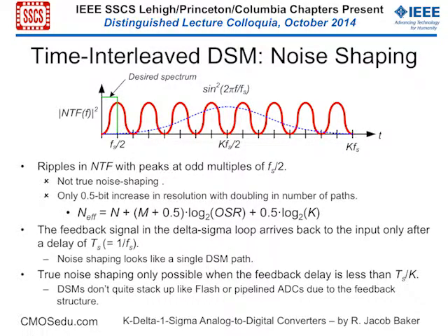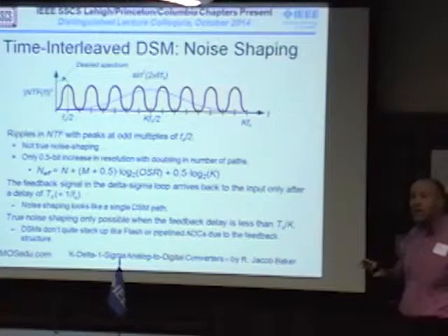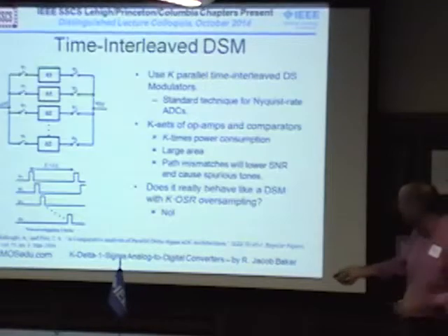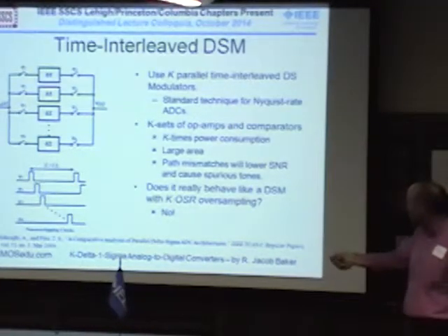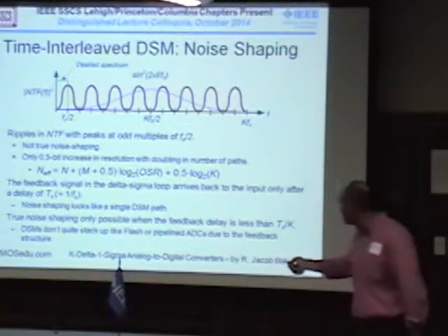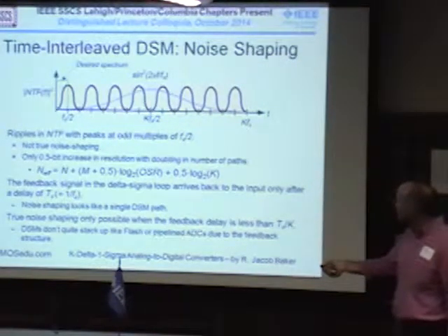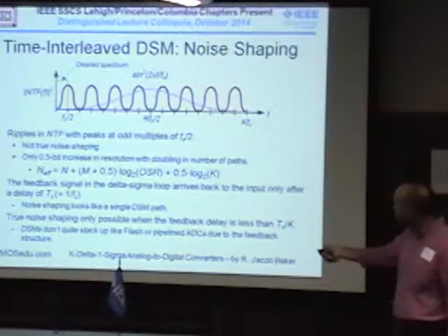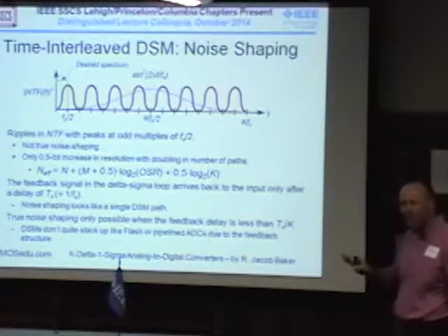What we want is what's in the blue. Because if we can get what's in the blue, then we've pushed the noise out to higher frequencies, and we've effectively increased the sampling ratio. There's papers that I reference here, there's this paper here that did this and proved what we're saying here. We built it and tested it. So you get a half-bit increase in resolution. You're squishing the noise, but it's squishing it in this area right here. It's not pushing it out like we see right here. Okay, does everybody follow that?